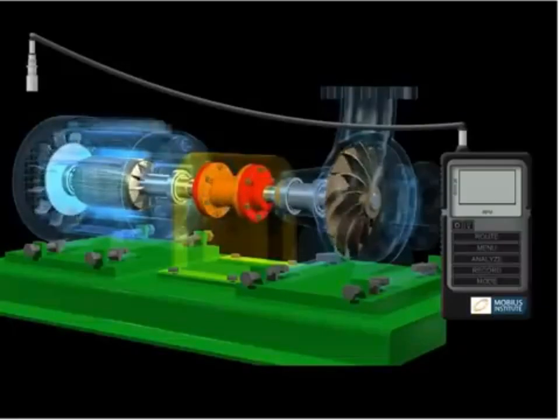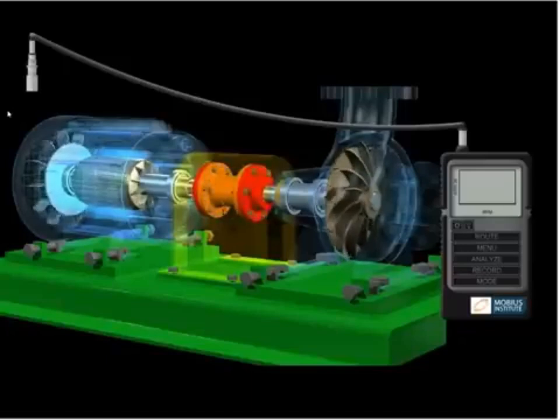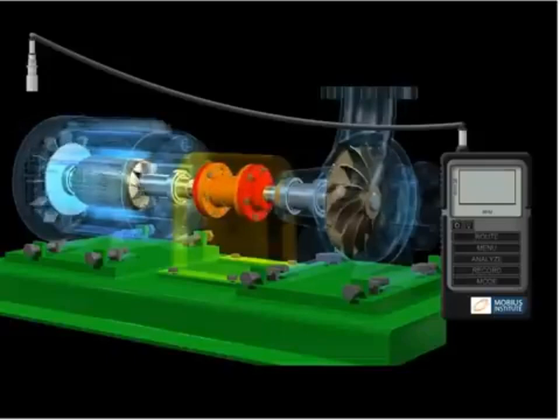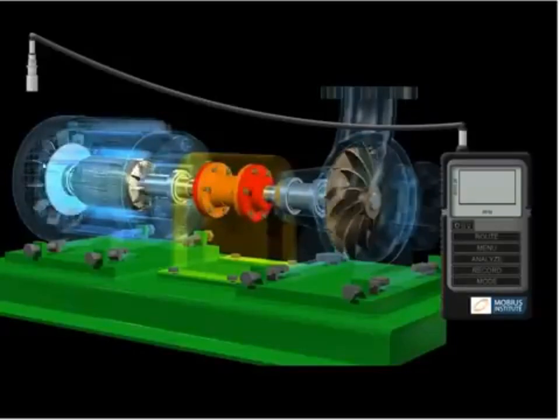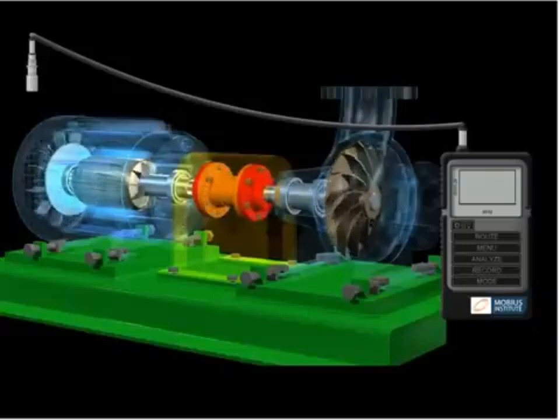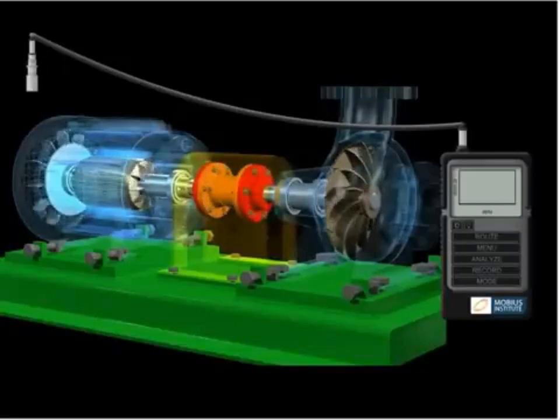So there's our machine. Now, as I mentioned before, the motor makes certain vibration, the pump makes certain vibration, and what's actually happening is as the shaft turns, there's magnetic forces in here, electromagnetic forces. There's the bearing vibration, the fan vibration, the vibration of the rotor bars and so on, and all of that transmits along and goes up through the bearing to the housing.